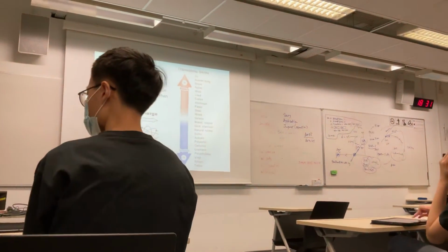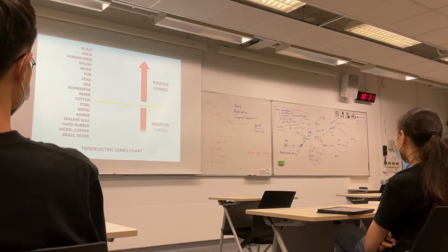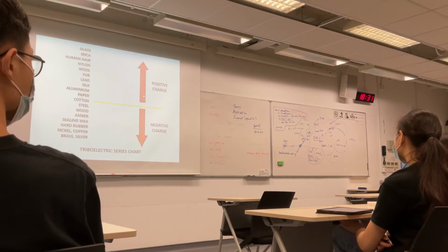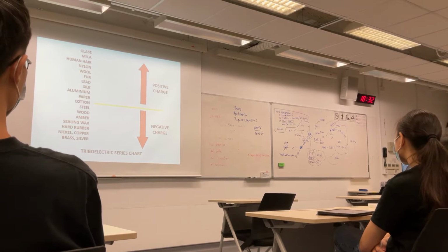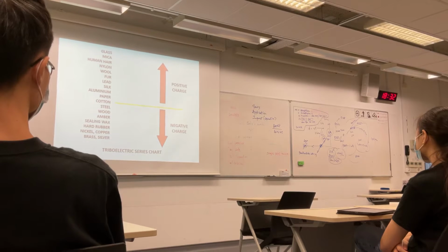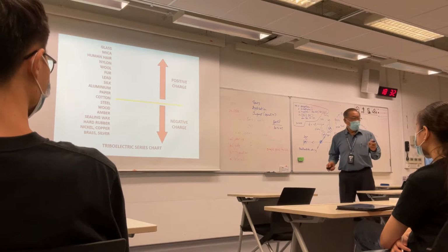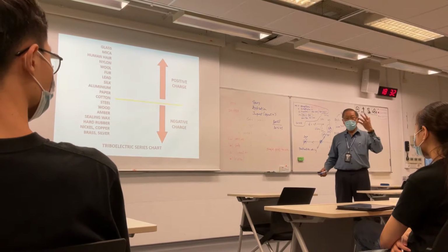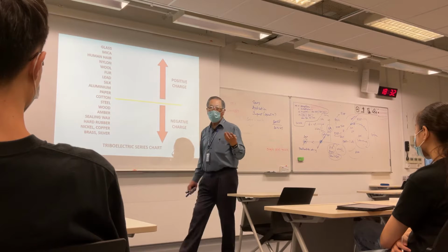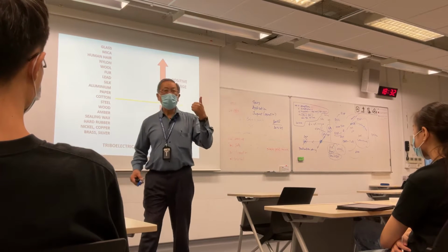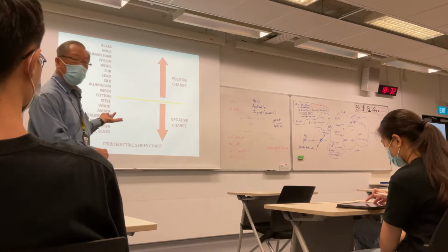Now this is important because there may be a question asked about this triboelectric series. Why is this so important? Okay? It's the gap. When you are designing something, you make sure that the gap is not too high. So this is to understand how to prevent generation. Later you will learn that there are 4 principles of ESD protection. What are they? First is to prevent generation. So to prevent generation, you got to understand the triboelectric system.